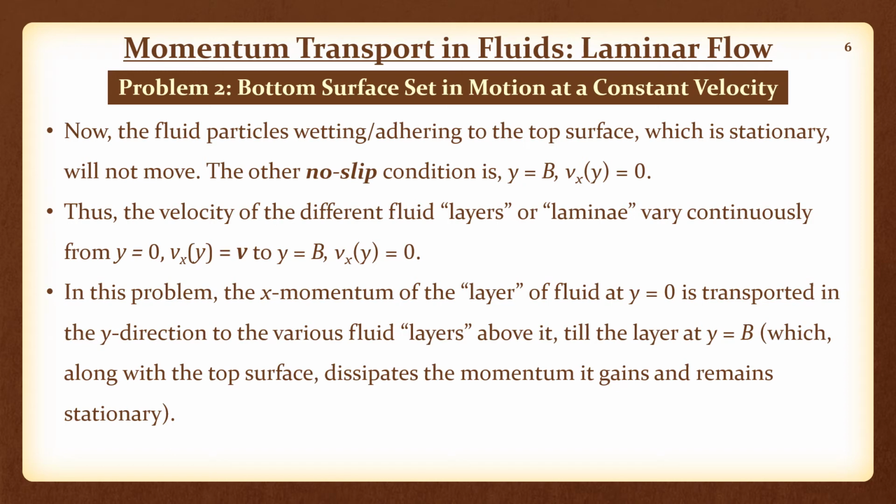And therefore, this momentum is imparted until it reaches the top surface, and the top surface, being a solid, does not slide; it does not move. The rate at which the momentum is to be imparted, once again to recall, the time rate of change of momentum, is force. In other words, it is the force that you need to apply to make the top surface move, because the bottom surface is moving through this fluid.